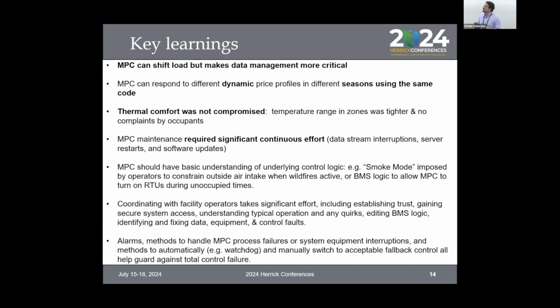So really the practical issue of coupling the MPC with the communication infrastructure of the building was the hardest part, because to be honest, changing from energy optimization to cost optimization was very, very easy and fairly seamless. And actually throughout all this experiment, we had to tune the parameters a little bit at the beginning, but then we didn't make any change to the code for all the testing, which I think is a nice testament to how flexible MPC is with respect, for example, to a traditional controller, where you'd have to design a specific controller for each of those scenarios to achieve similar levels of flexibility.